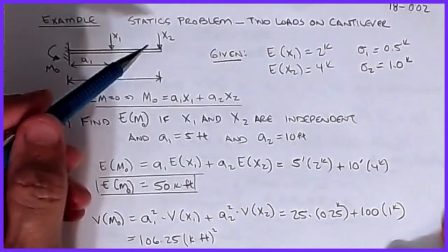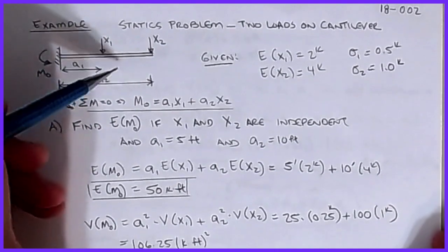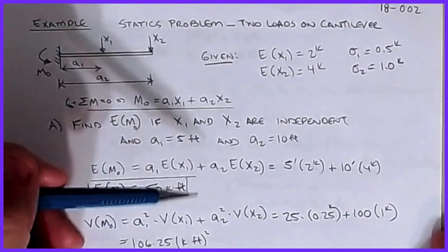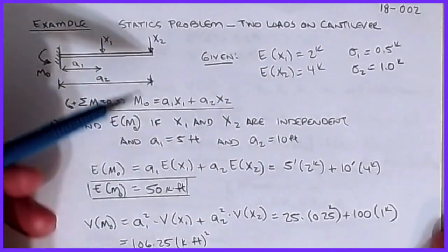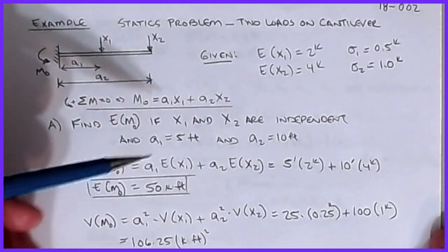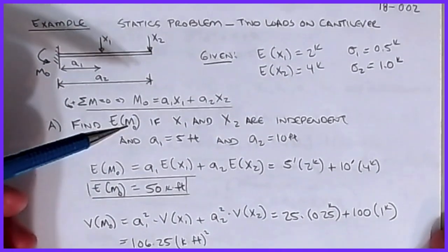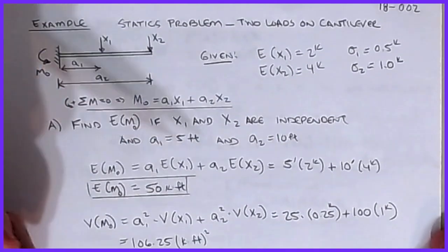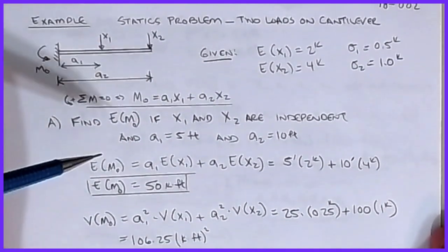And in the real world, this is the way loads are treated. Part of the challenge of a designer is to figure out how much load I need to design for, and what I can start to predict. So we're going to show you the method by which a lot of the building codes, whether it's AISC or ACI or any building code, has some sort of safety factor that has its roots these days in some sort of probability mechanism. So this is almost like a risk and reliability study that we're going to look at.